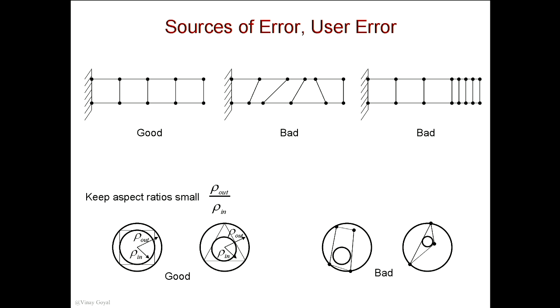A triangular element that's highly distorted will look like that. So clearly this is not a good element. In some cases you have no choice, and so you may have bad elements and you can't do much about it. In those cases, you want to use stress fields, far field stresses, to do your calculations.